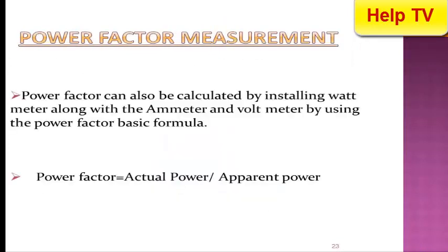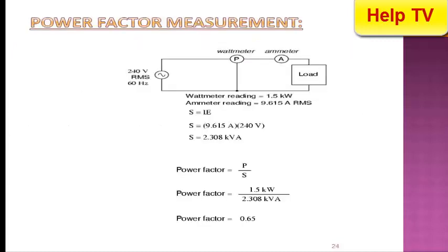Power factor measurement. Power factor can also be calculated by installing a wattmeter along with the ammeter and voltmeter by using the power factor basic formula. Power factor equals actual power divided by apparent power.